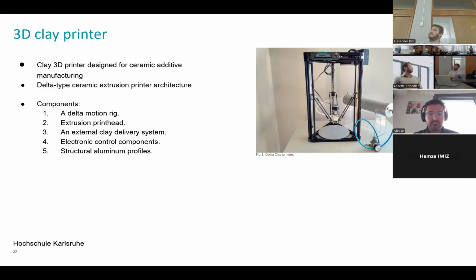Currently, we are also working to make some bricks in clay, which are going to be used for cooling interior spaces. Clay has a property that its porosity can evaporate water that is coming from the rain. And also the air that is coming through this clay and these pores can evaporate the water and cool the interior spaces. So for that reason, we started to evaluate the environmental impact of the 3D clay printer.